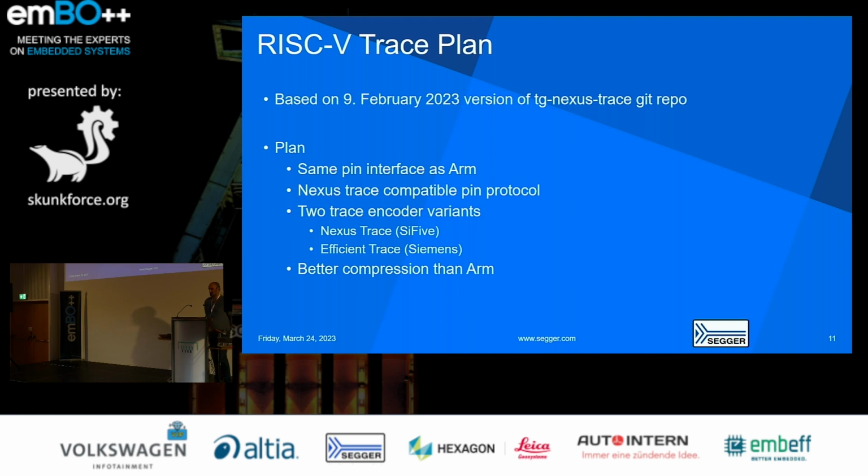In reality, they're both pretty much the same. But today I will focus on the Nexus Trace standard, simply because this is the only standard that was fully implemented first and published, and because the whole interface from encoder to the trace pins, everything is called Nexus in this area.